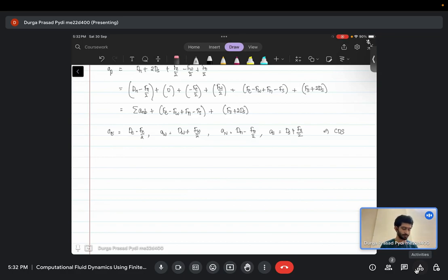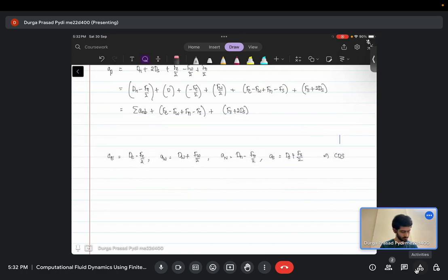Now once we have the coefficients, the first step is to essentially get your diffusion coefficients. Okay, maybe I should have written this later. First step is to get your coefficients. dE is essentially gamma E in our standard convective diffusion form, so it will be, for the east face your area will be delta y, so gamma E delta y by delta x, and dW will be gamma W, d north